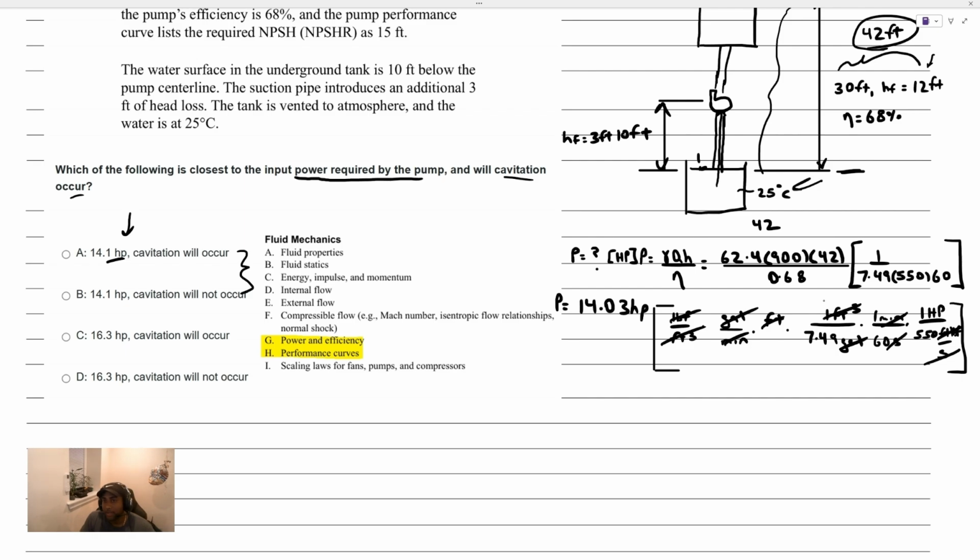Essentially, the pressure drops below the vapor pressure at the entrance of the pump, and you have a liquid vapor mixture that enters the pump. Those vapor bubbles end up collapsing in the pump since the pressure increases enough to turn that vapor back into a liquid, and that causes corrosion of the impeller. That's the idea of cavitation.